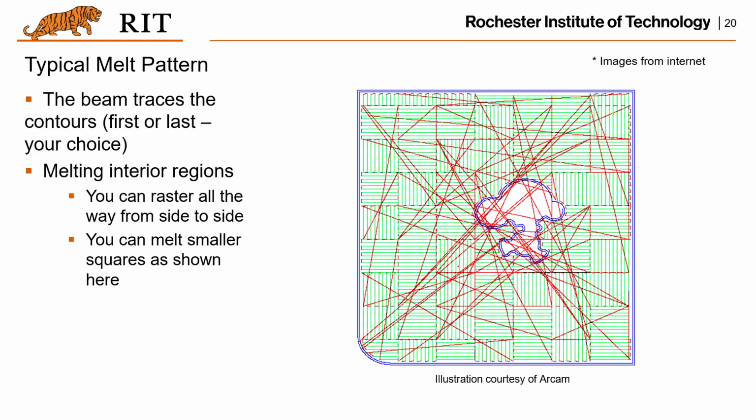Here shows the traces to generate the contour. Of course, the different tool paths, different such kind of a trace would affect the mechanical properties of the part. And that's also a very important point for the manufacturer of the EBM machines to look at.